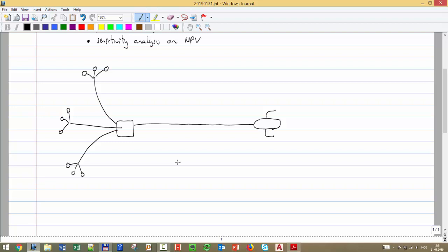So I taught you last class how to make this equilibrium calculation to find rate, but based on a single conduit. If you remember, the case we had last class was a simple well, a single well. We had a pipeline, and then we have a separator. And that we know how to solve, right? You already know. But how do I tackle this more complex system? We are going to discuss, let's see if we have time, how we deal with this, what we call a network.